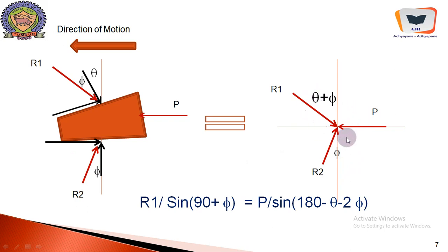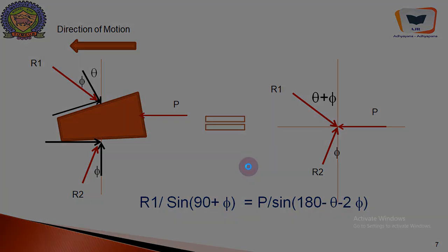Therefore in most of the friction problems, the free body diagram ends up in three forces which will keep the wedge or the block in equilibrium. Therefore Lami's theorem can be applied. Okay, wedge problems, typically speaking, are very easy to analyze and solve, though they look a little tough seemingly.